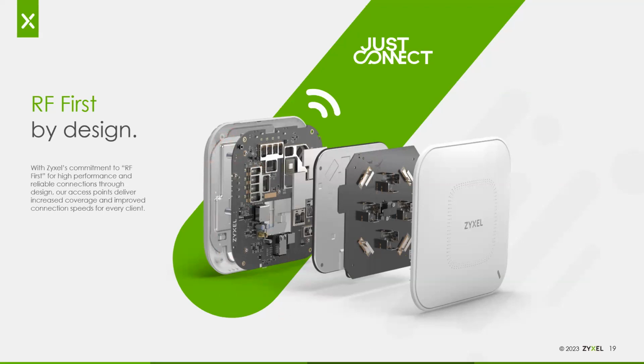If you look at some of our cheaper competitors out there, they don't even have vent holes to let heat out. And that's a bad thing. And it's one of the reasons why they offer only a 1 year or 2 year warranty, is because over time with a solid state component like this, if the heat builds up too much, it can cause failure, either failure of the solder joints or failure of the individual little switches that are part of the microchips on the PCBA. So our design pulls that heat off the board and vents it out, making sure the board doesn't overheat.